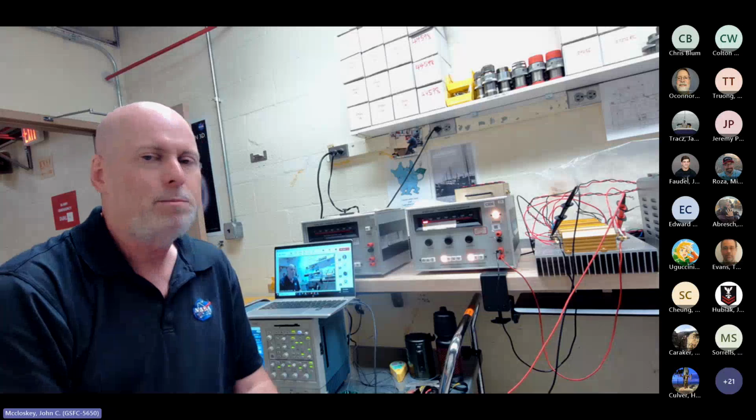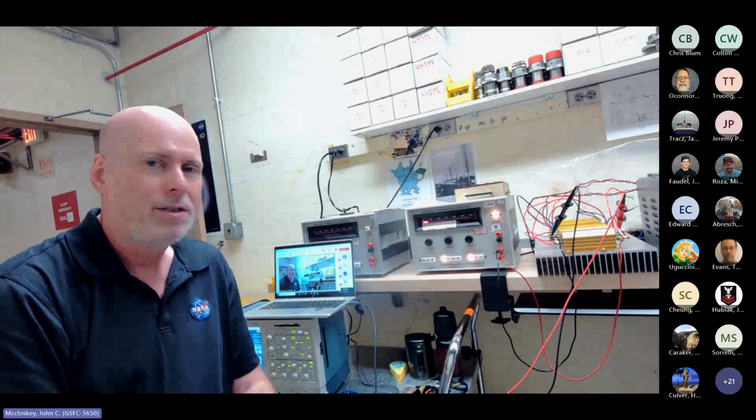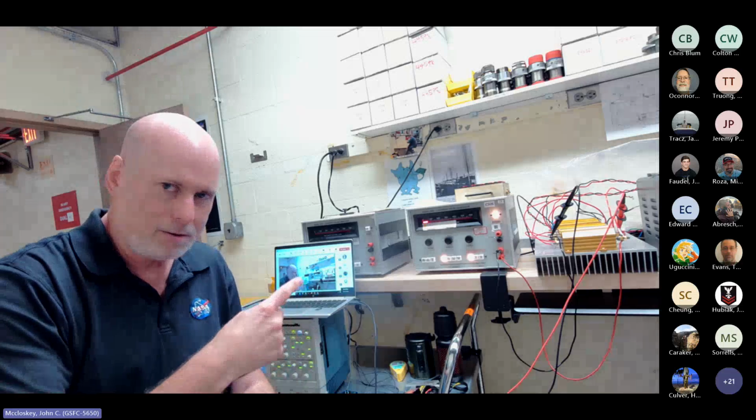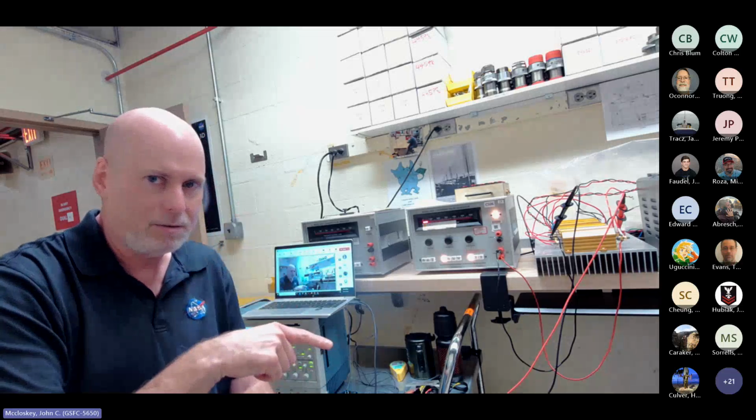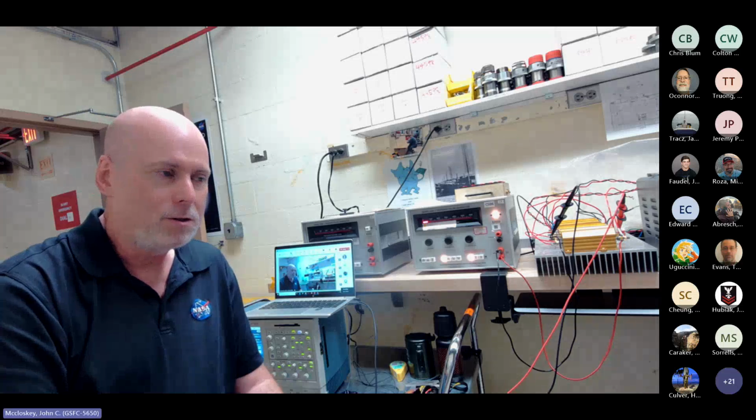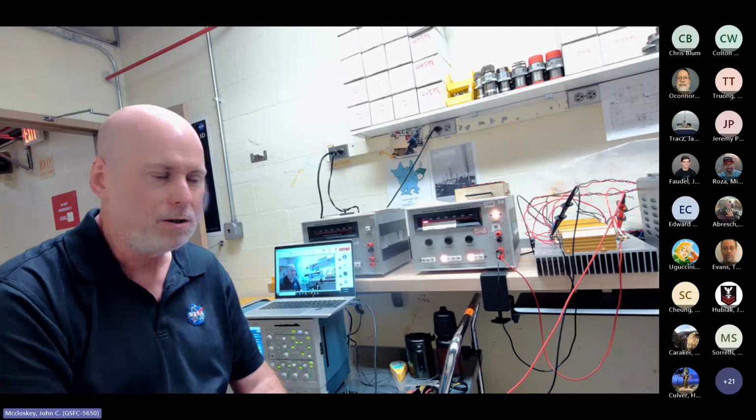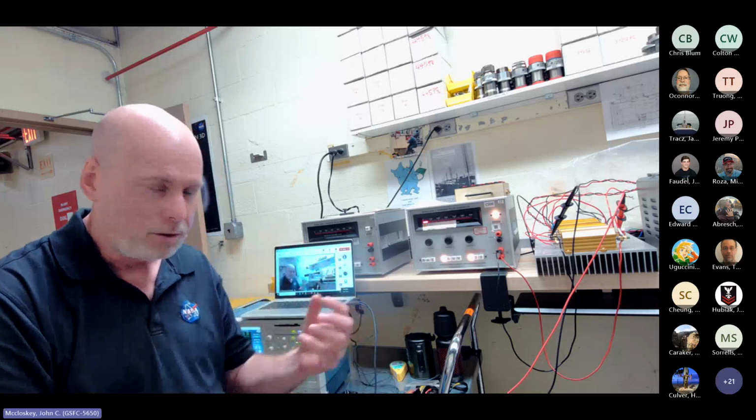I never got the scope to trigger once when we were turning any equipment off, not once. So that underscored that the inductive kickback from turning equipment off was not an issue. Their power system also had that big capacitor bank inside their PDU that absorbed all of that energy from many potential turnoff transients. The turnoff transients just were not an issue.